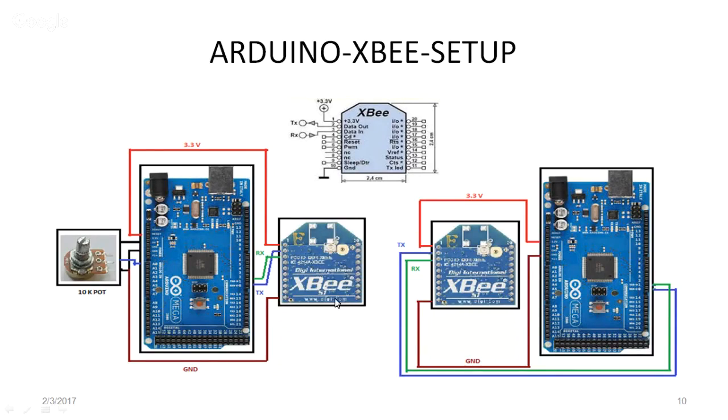Here I have shown you in this figure that we have a 3.3 volt first pin. We have to connect your 3.3 volt pin to your Arduino Mega board. There is your 3.3 supply. So please be connected. After that, we have two pins, that is your TX and RX. These are the pins responsible for transmission and receiving of your data. In this Zigbee module, we can connect your system as a transmitter and as a receiver also. The Zigbee module is basically a transceiver type of communication device. You can use this as a transmitter as well as a receiver.